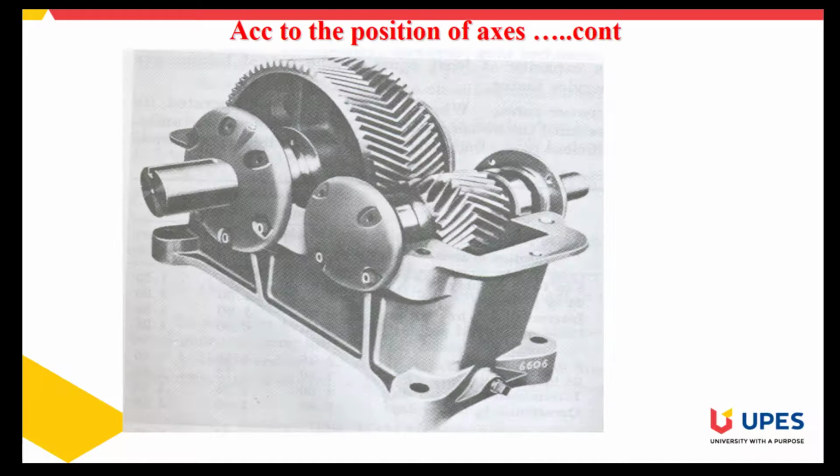Now, if you move further, how can we overcome this problem? There is a solution. To overcome this problem, we can use a pair of helical gears, or you may say two different helical gears which have different helix angles. One has a left hand helix, and the other has a right hand helix, and these two gears are put together and then used.